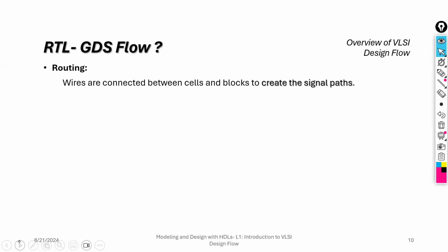The different approaches that are there: global routing, detailed routing, channel routing. So these things will come under the routing concept. The routing concept is just to provide the interconnections among the standard cells.